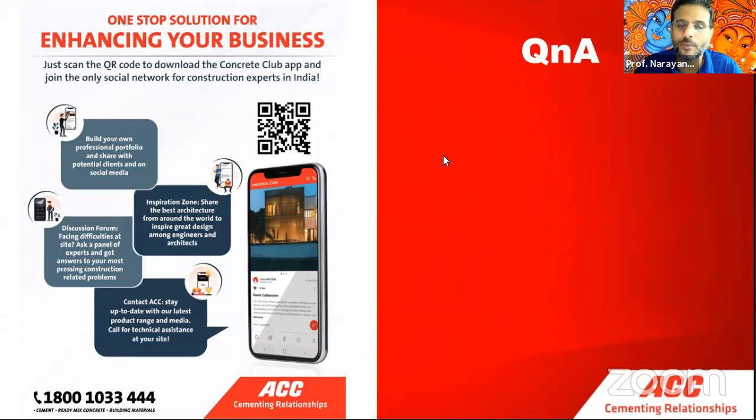Testing size of cube for UHPC. You can afford to use slightly smaller cylinders or cubes because you're testing mortars, essentially mortars, not concrete. So there is a standard, there's an ASTM standard that's out there. Now I forgot the number, but you can look at that. Durability, we'll get there. Feasible to use UHPC in a high-rise residential project? Absolutely, it is. I'll show you some design scenarios as we go later. It seems the rate of hydration will be higher than any other concrete.